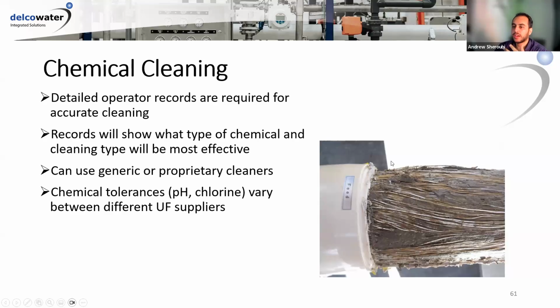And if you know that you're dosing chlorine directly into a well, or you have to dose chlorine before a UF, there are membrane manufacturers that have ones that are more tolerant than others. So there's some room to work with here.